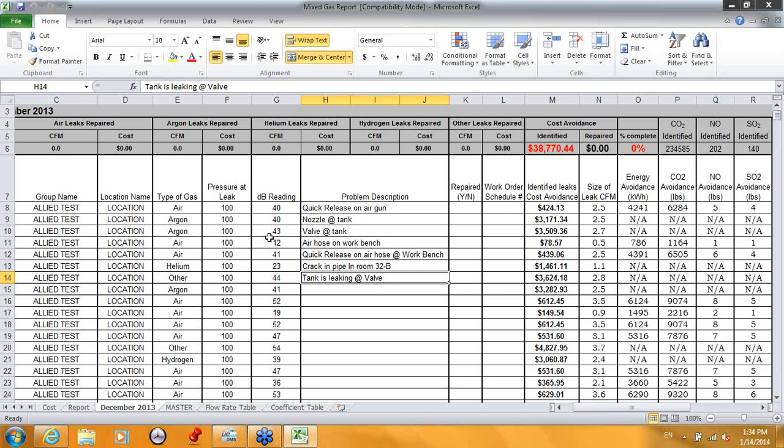This report is basically a conservative report. So if you back away, the dB value will drop a little bit. You want to be very conservative with your readings, because if you're on top of every single one of these leaks, these numbers will actually explode, so they're not going to be the true value of the leak itself. Okay, so just bear that in mind.